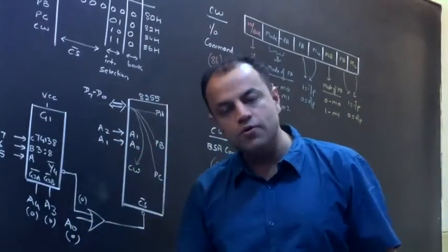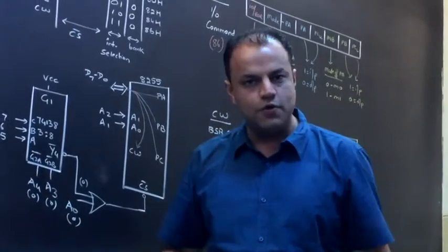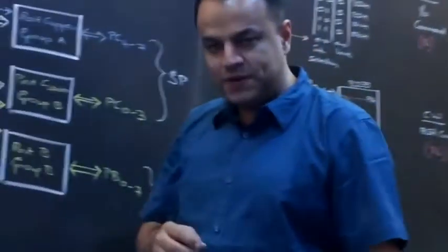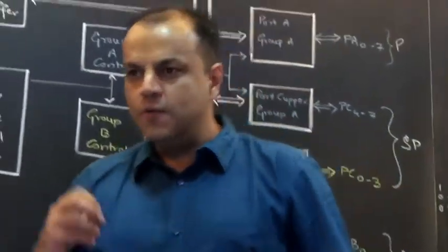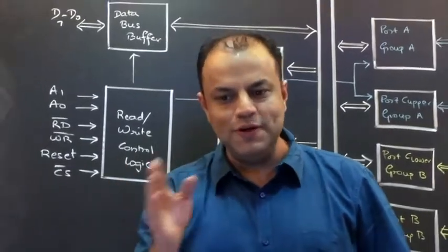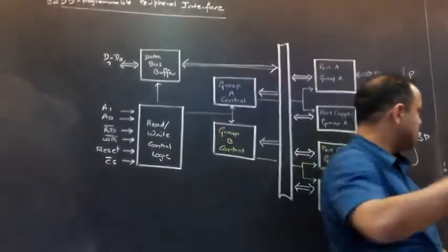Here I am not doing the whole process again because it's not required. Once you know designing for one chip, you know it for all chips. The concept is the same. So in 8086, we never give A0 inside any chip. Why? Because we don't want consecutive addresses. We want alternate addresses. Look here.